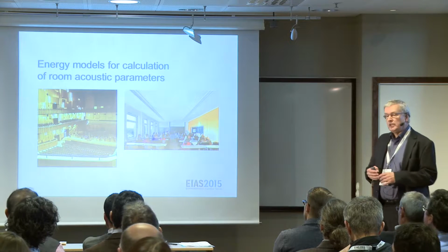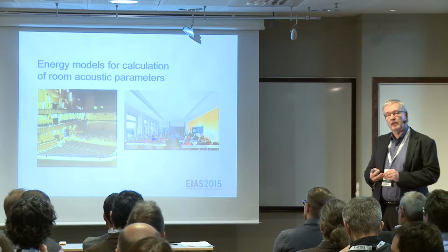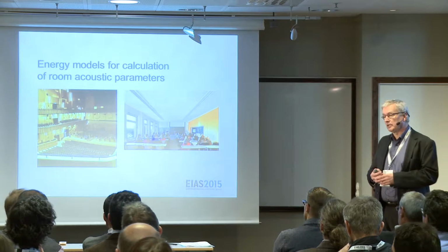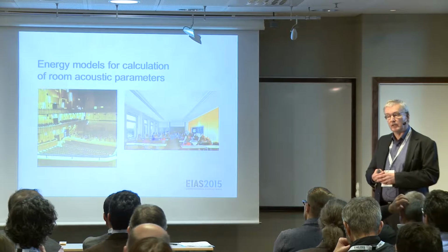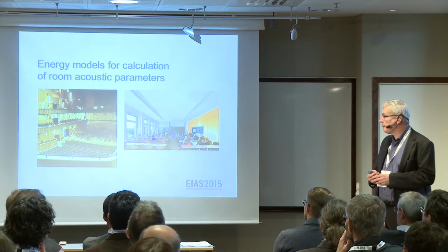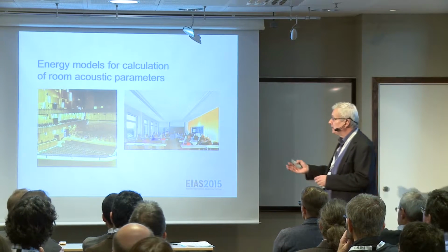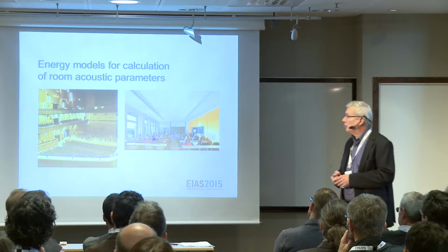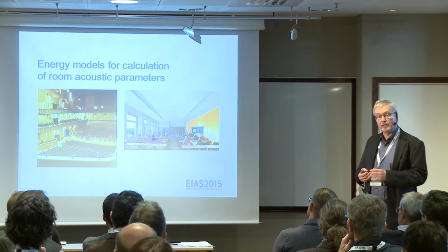So then, of course, from an engineering purpose, it's quite good to be able to estimate those parameters as well. And we have, as you know, formulas for reverberation time, but not that much for speech clarity and strengths. For concert halls and large spaces, there is a model developed by Barron for calculating the strengths.